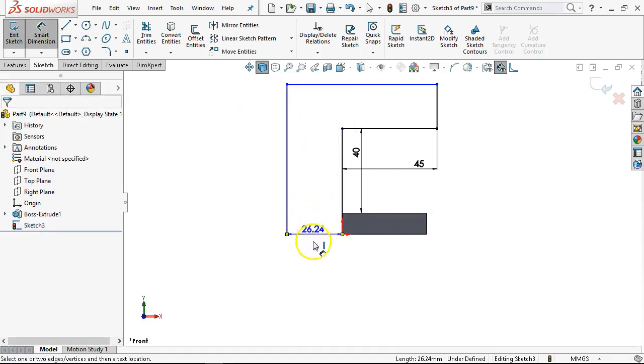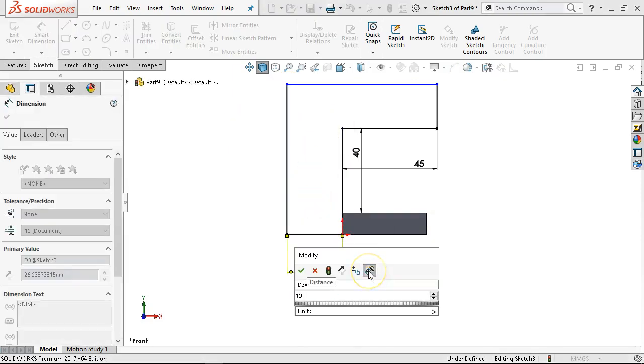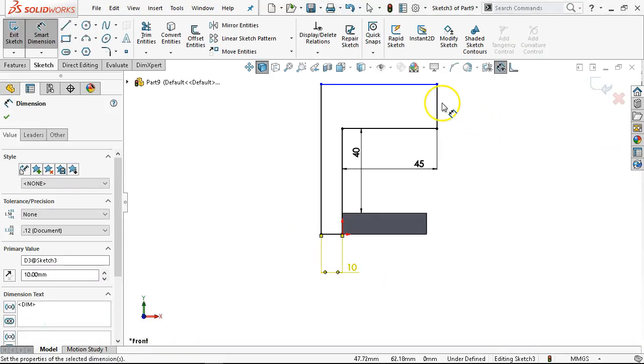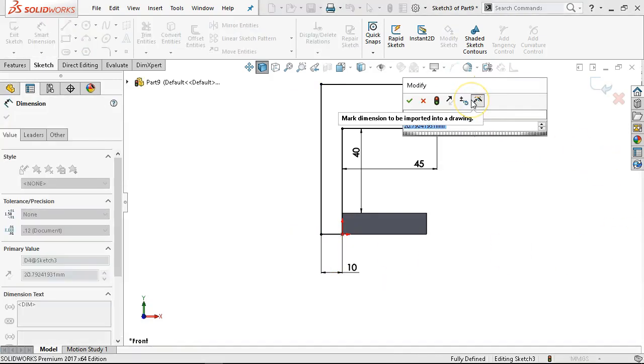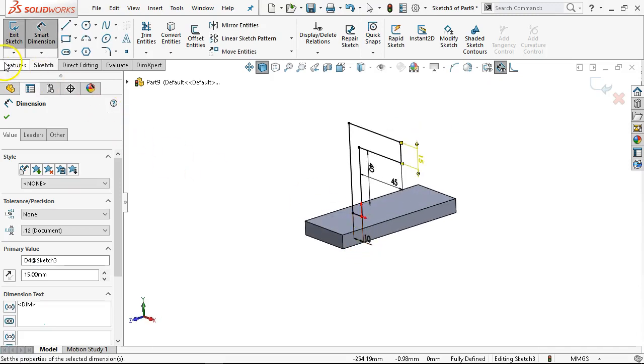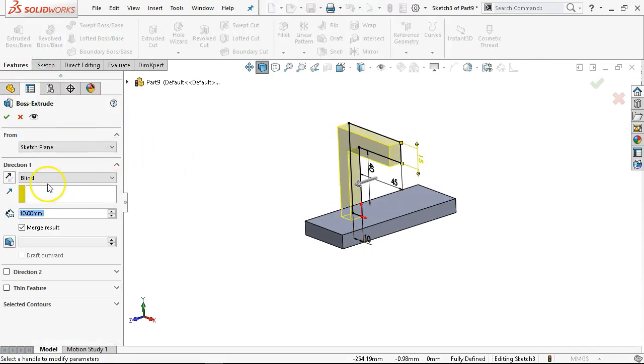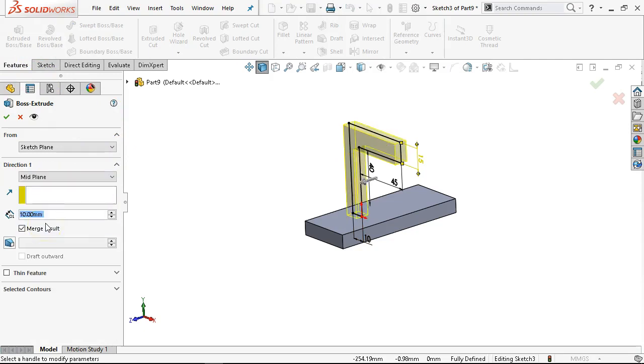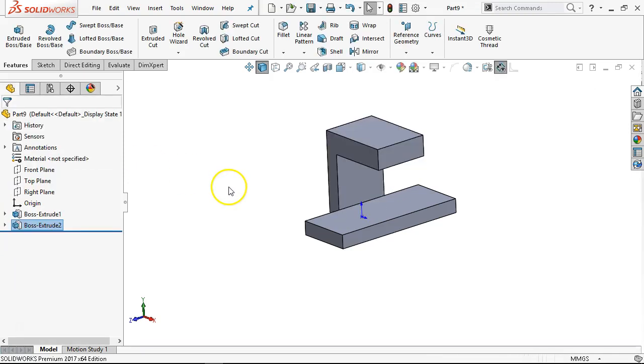I get the geometry built out for me, but I have to complete those relations. All right, so 15 on the vertical, 10 on the horizontal, and then we can extrude. So I guess the takeaway is that you made a choice, found out it didn't work out. Doesn't mean you necessarily have to back out of it, but you have to be prepared to take that different path. And midplane on 40. We'll set the distance.